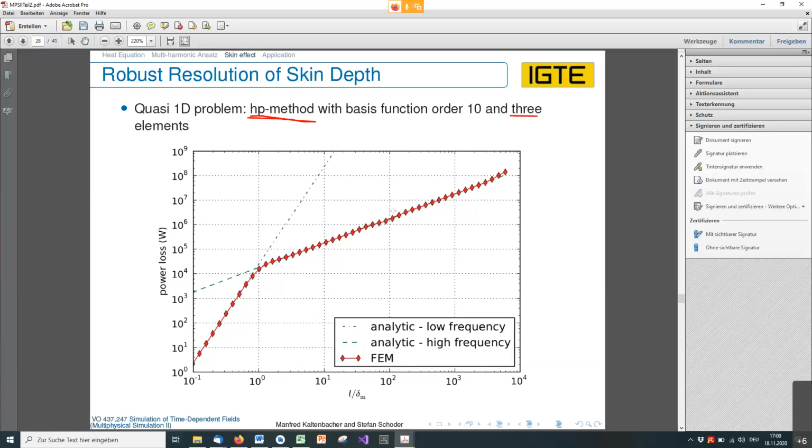That's basically it for resolving the boundary layer. Be aware that it could be an issue that you under-resolve your boundary layer. And typically you should do a grid study on the boundary layer resolution in order to prove that your finite element model really resolves what you would like to resolve.